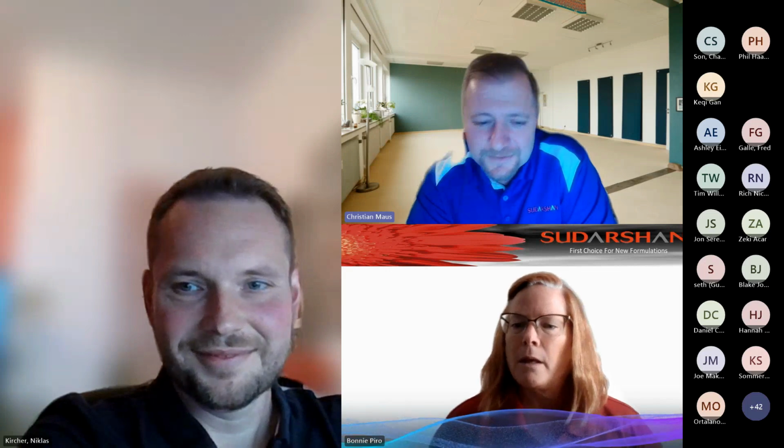And we have also a guest here with the name Saurab. He just mentioned it might also be analyzed by the filterability test. That is absolutely true. Like the filter test which we just did, you will receive a so-called filter index. So you're taking the time of the first filtration and the third filtration divided, and you get an index. And also this can be used to find out when the milling is done here. Yeah, good point. Good idea.